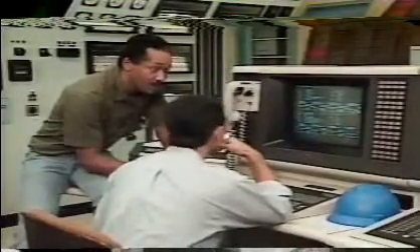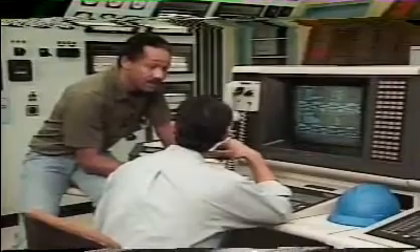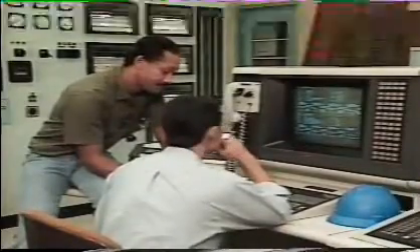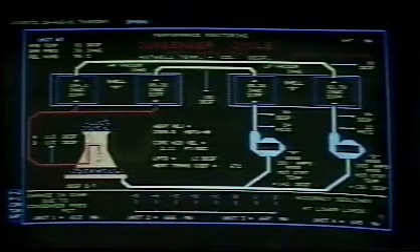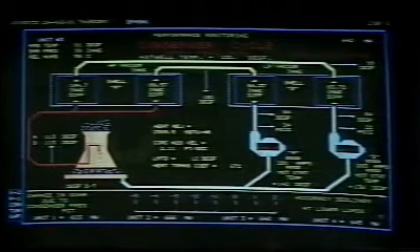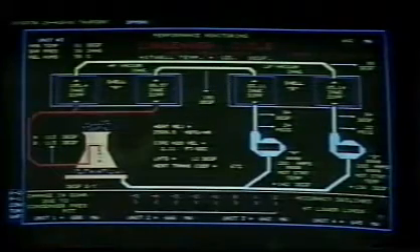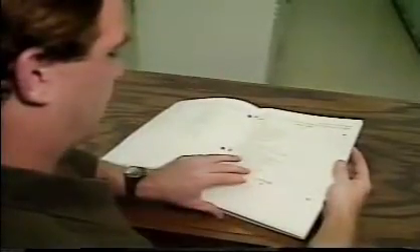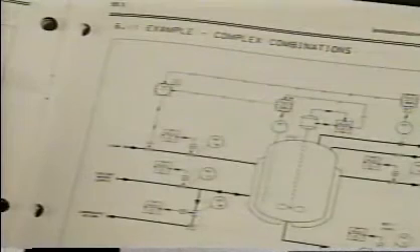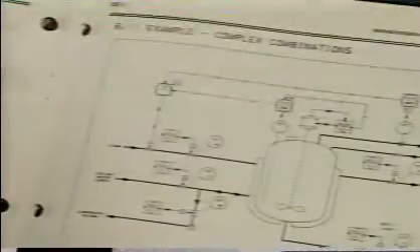Digital control systems provide versatile and efficient process control and data acquisition in many industries. Terminology and symbols used to represent control systems have been expanded to include digital technology. Standards have been developed to provide universally accepted symbols that represent digital as well as analog control systems. ISA's Standard 5.1 contains definitions of process terms associated with digital technology. The symbols and designations used to illustrate control systems are shown along with sample diagrams that serve as examples of how they are used.